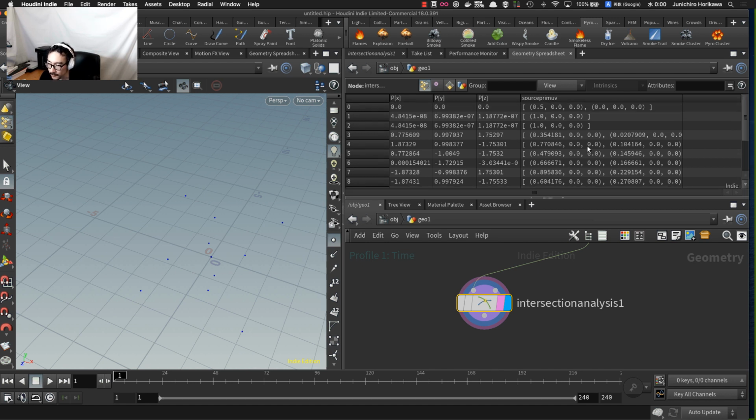So what I'm gonna do next is to just pick the first value for each source primitive UV at each point. Then I'm gonna add it inside the float array, then sort it out based on the value, then use it in order to split the curve.